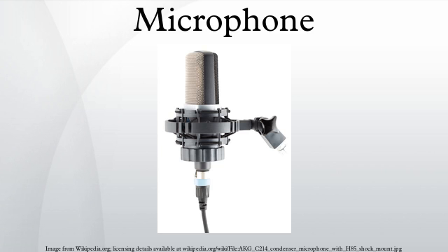The wavelength of sound at 10 kHz is little over an inch. The smallest measuring microphones are often 1/4 inch in diameter, which practically eliminates directionality even up to the highest frequencies. Omnidirectional microphones, unlike cardioids, do not employ resonant cavities as delays, and so can be considered the purest microphones in terms of low coloration.